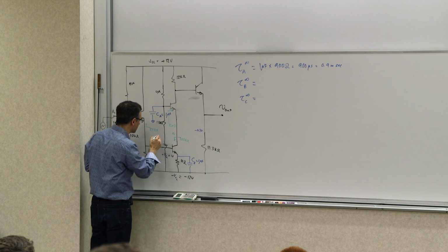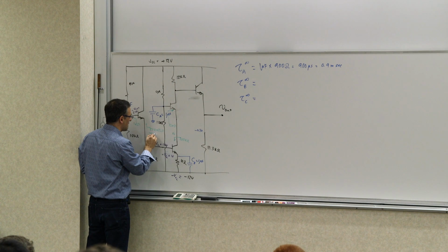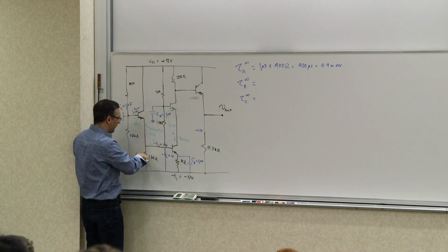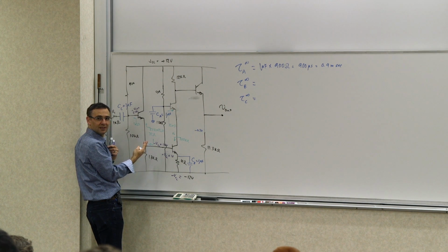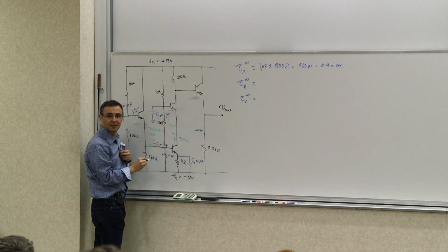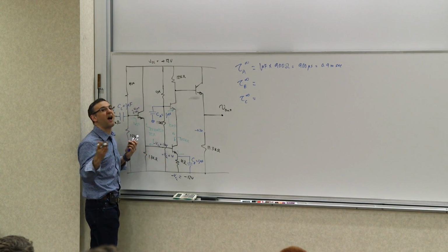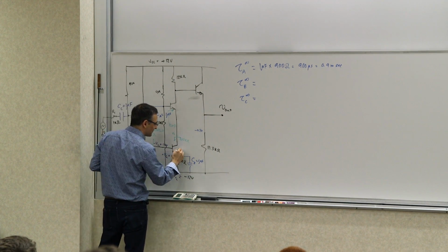Beta plus 1, beta. 10 ohms. So that's 35 ohms. This is 35 ohms parallel 1.7 kilo ohms. It's 35 ohms. Right? Divided by another beta when you look through here. So that's 0.35 ohms plus 25 ohms. So it's nothing. It's the Rm, 25 ohms.